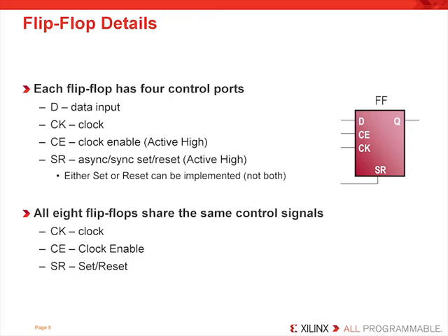There is no local inversion for either of the clock enable or the set or reset ports. You also need to know that the set reset port can be programmed as either a set or a reset, but not both. Unlike older architectures, there is not a separate set and separate reset port available on these flip-flops. So if you want both, either the set or the reset functionality will have to be generated from a LUT, and thus be a synchronous set or reset.